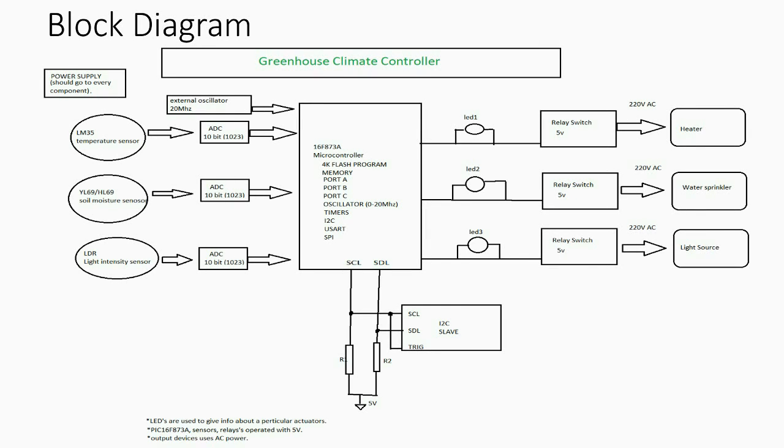It has 4K flash memory, and it has memories like EEPROM, and it has three input output ports. Port A has an inbuilt analog to digital converter, and port B has I2C communication ability. We have to give an external oscillator of 0 to 20 megahertz.